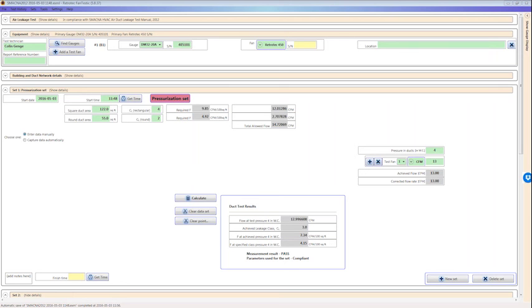One of the failings in a lot of commercial systems is that they've got a blower running and 25% of the air is leaking out before it gets there. That blower is running overtime. It's oversupplying the units closest to the blower where the pressure is the greatest, and it's undersupplying the units at the end of the building. The same kind of problems we run into in houses.